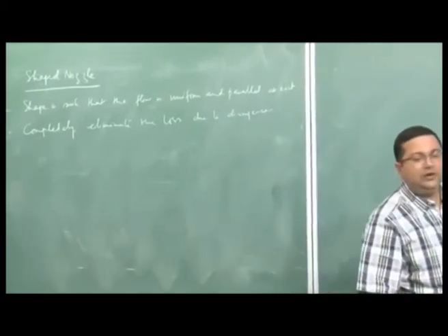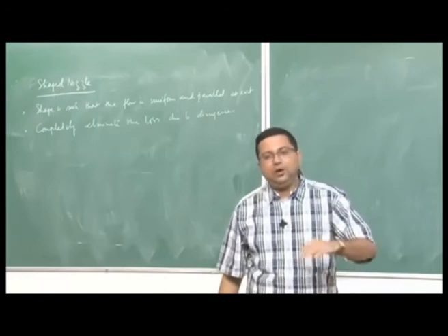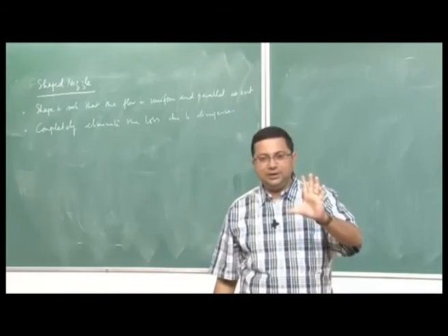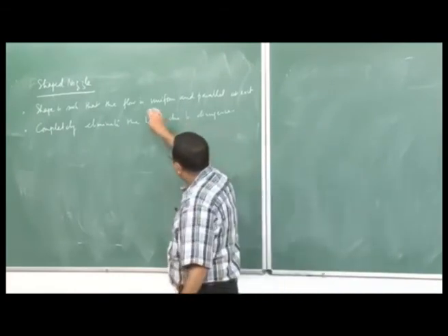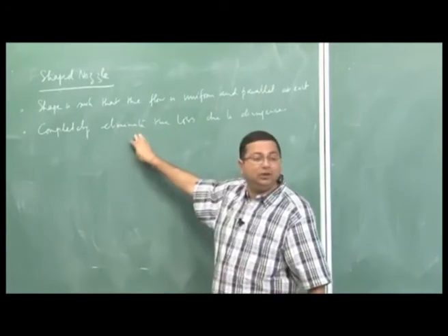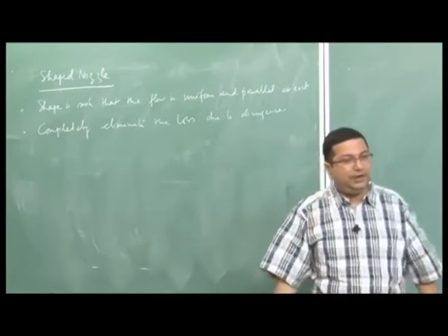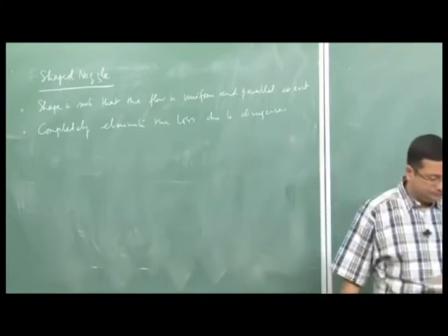In the conical nozzle, we have seen that there is a loss in thrust, and that loss was because of the 3D effect, which is because of the divergence. So, that loss is called divergence loss. If we can provide a uniform parallel flow at the exit, it will completely eliminate that loss. Okay, lambda, we can get lambda equal to 1. So, that is the aim, it will completely eliminate loss due to divergence.